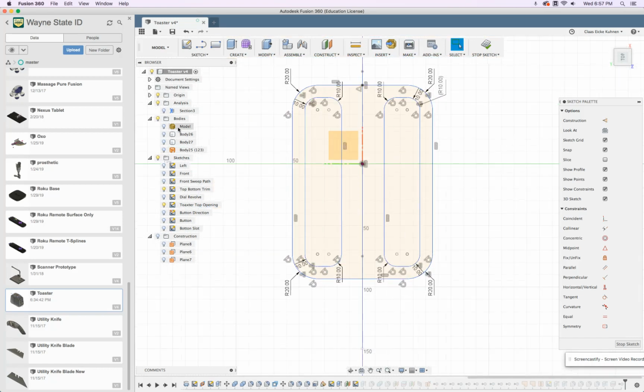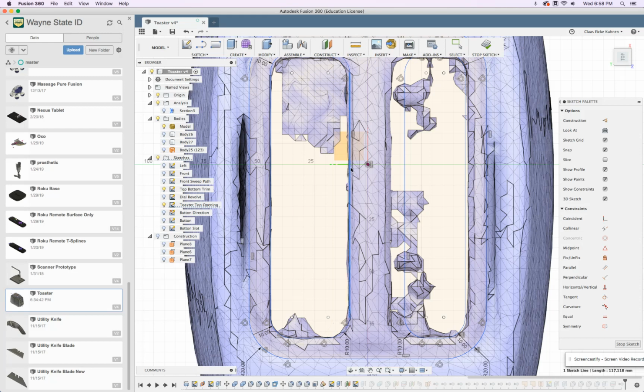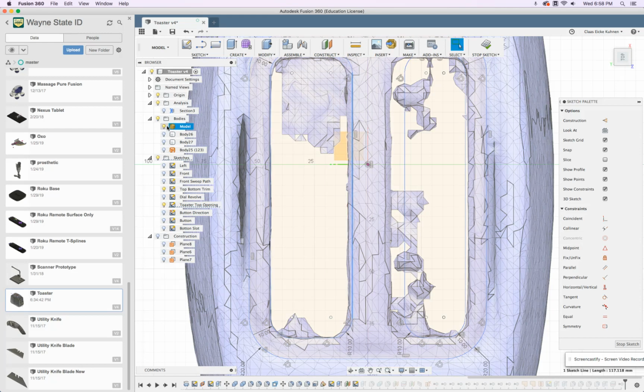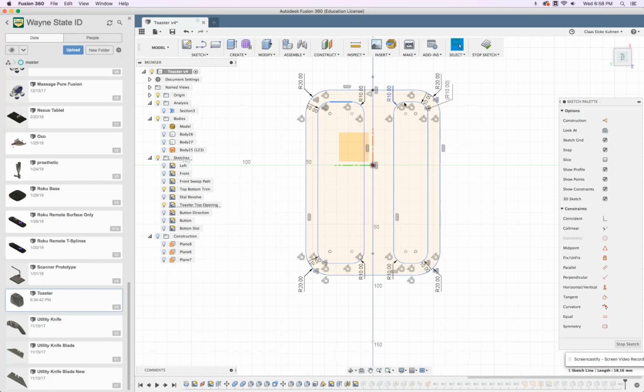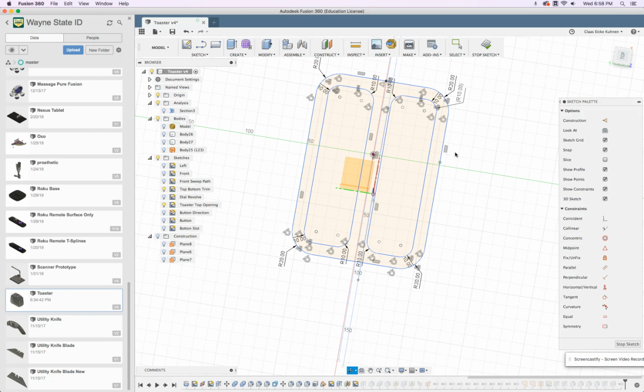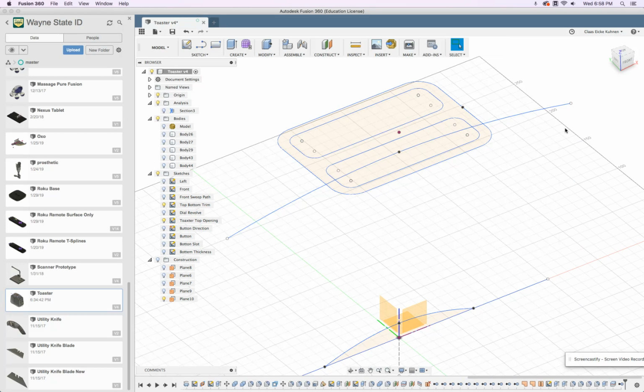So that looks symmetrical. What about the width? That's not. This line here I push over to there. All I need to do is now this and this line, they should be equal. See, that made this other one as wide. Very good. There we are. So with this, create it. Stop sketch.